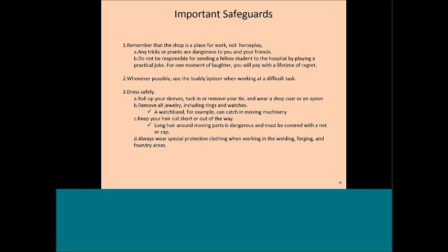Talk about dress safety, and again, sleeves rolled up, no long hair. It's going to be tied up if it's a ponytail, especially the ladies. No jewelry, and again, no rings or watches.